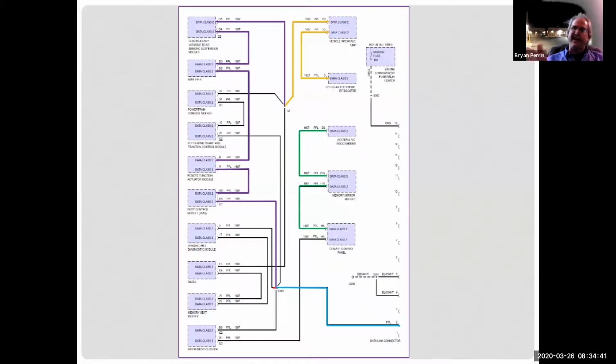So you see the fine difference that I'm splitting there? Yeah. So each manufacturer can have their own OBD2 type sensor or scanner or something? Yeah, each manufacturer has their own scanner. There are two parts to the system. One part of the system, if the car is OBD2, it has to talk on a certain protocol line. And then the manufacturer can use other pins to talk to whatever it wants.